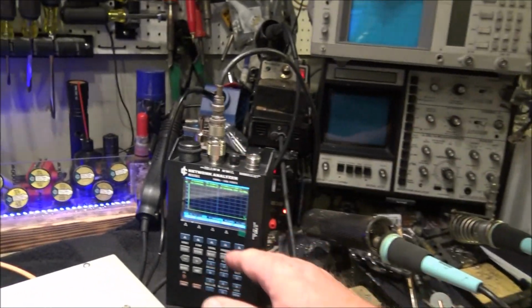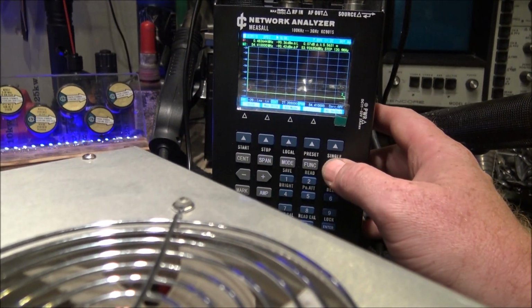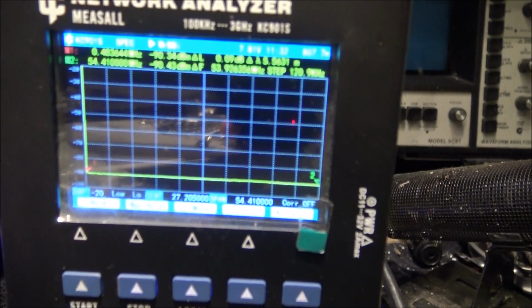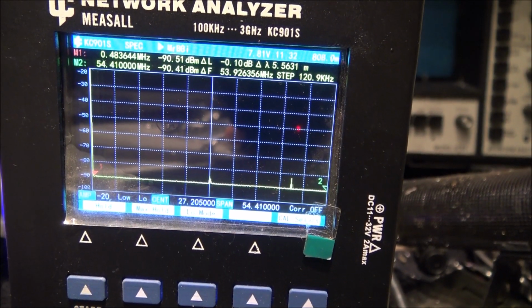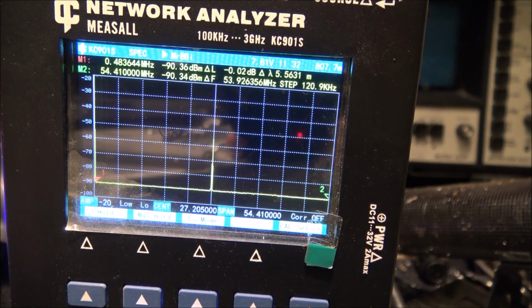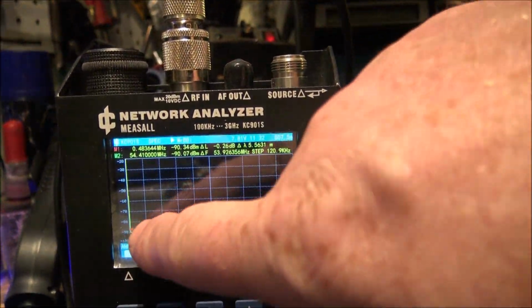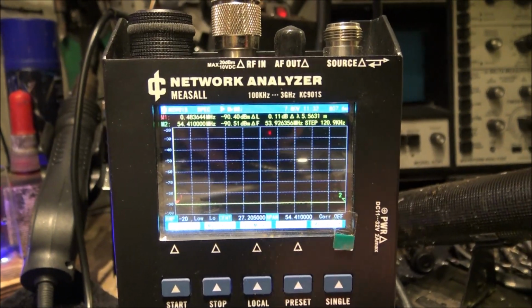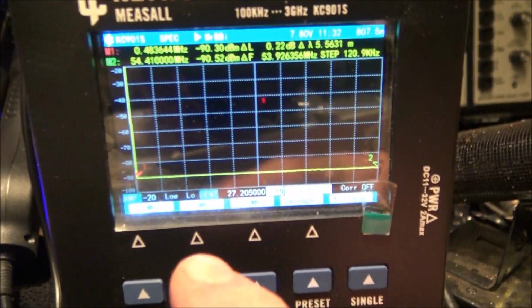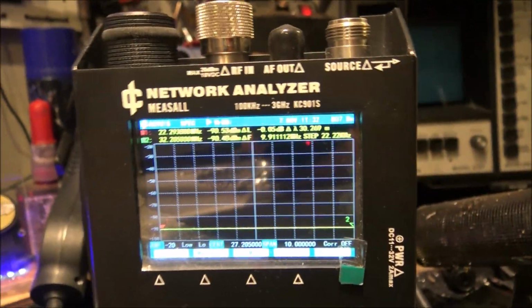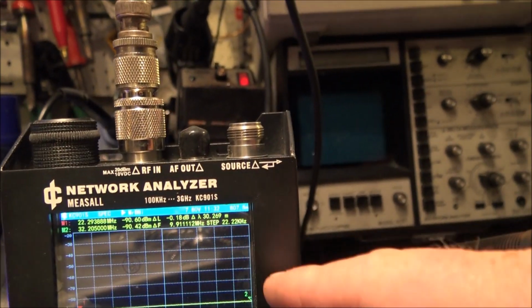So we've got our spectrum analyzer set up. Now let's see, we've got this set to run. We are in run mode. We're going to do our baseline shot. We're at negative 20 dB. Hello, audio. So now we can see some very slight harmonics come off the bench radio. We're seeing a little signal spike over here and another one over here. Let me go to span, and we're going to take this down to 10 megahertz. Okay? So we're 10 megahertz wide now.